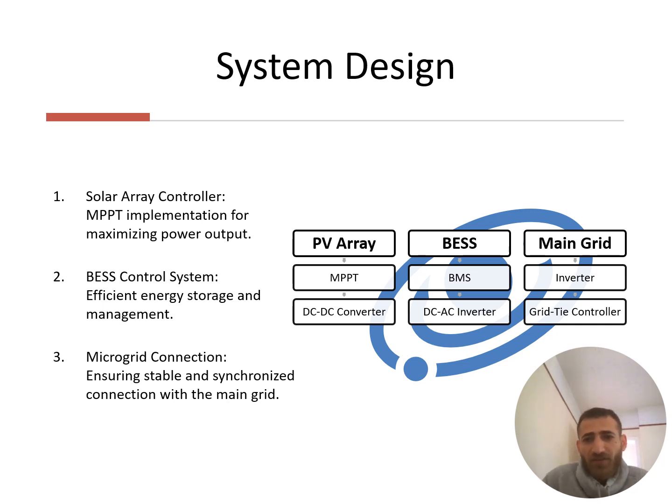The PV array connects to an MPPT controller, as we can see, which optimizes the power output by adjusting the DC-DC converter through adjusting the duty cycle of the switch, sorry. And this converter regulates the voltage from the PV array to match the requirements of our system.